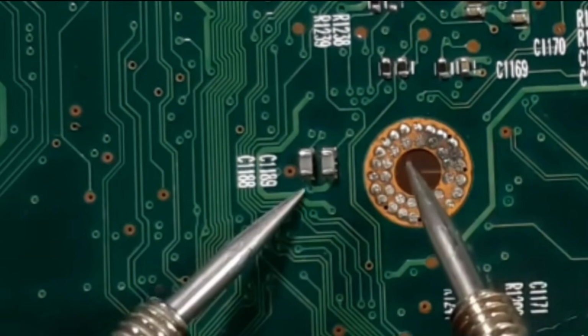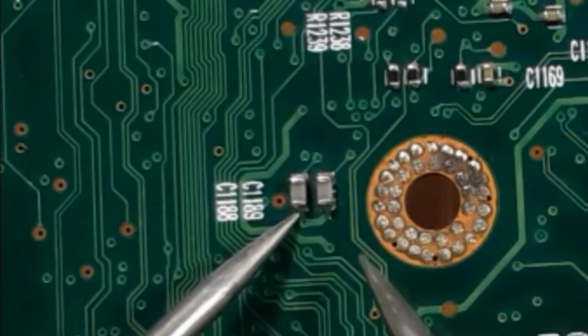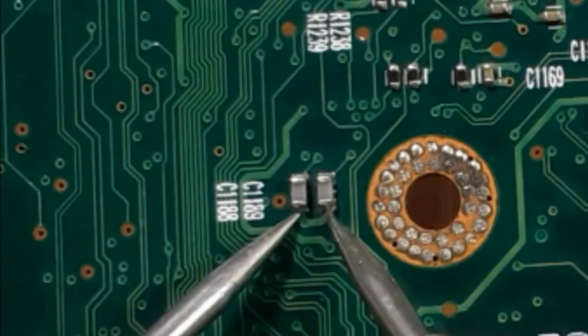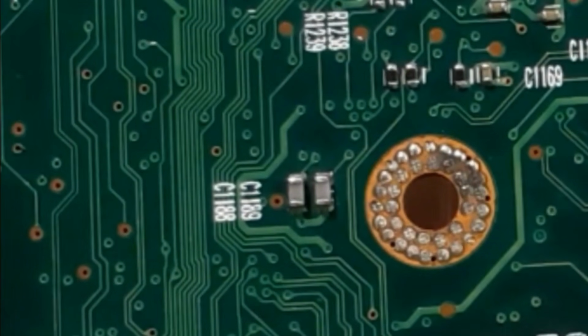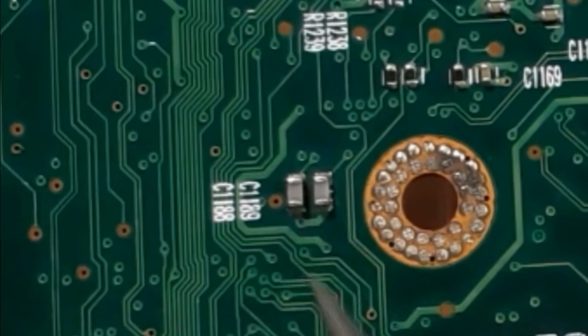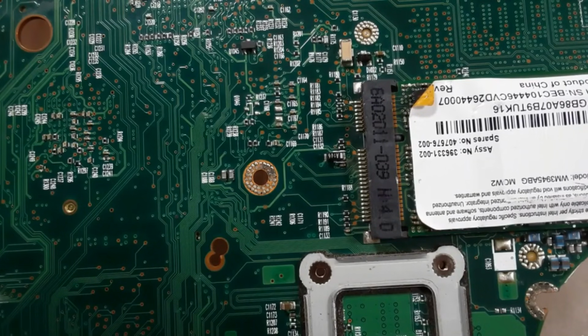Let's check these 2 capacitors. So let's check this capacitor. Okay, as you can see, we have a continuity bus. Why? Because we have this bus. So I know that these 2 capacitors are connected together directly from the motherboard without using the schematic. Why? Because I know how to use the buses.